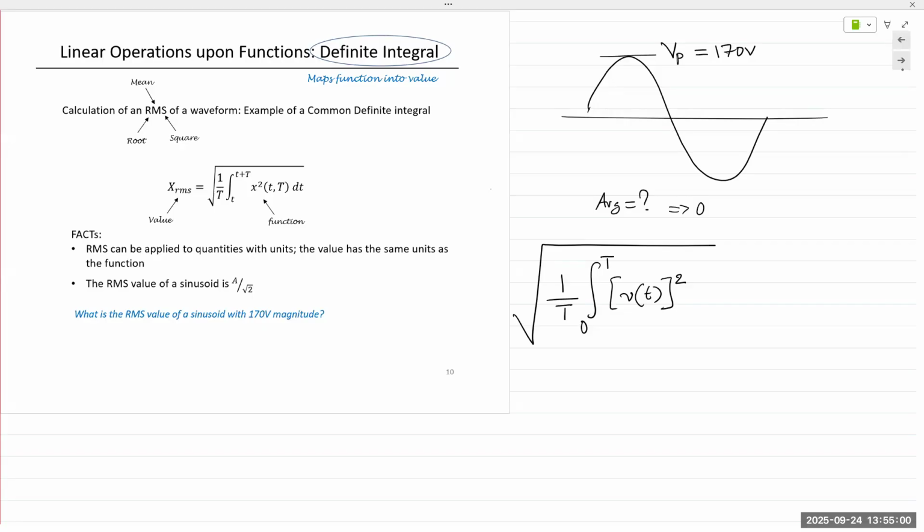Remember, it's 60 hertz. We just said it's very low frequency compared to everything else that we use, but 60 hertz is still fast, right? It's going up, down, up, down 60 times in 1 second. It goes from 0 to plus 170, then goes back to 0. That's only 1/120th of a second. And in the negative half cycle, it goes to minus 170 and then comes back up to 0. It does this entire cycle 60 times. So plus 170, minus 170, a total swing of 340 volts.